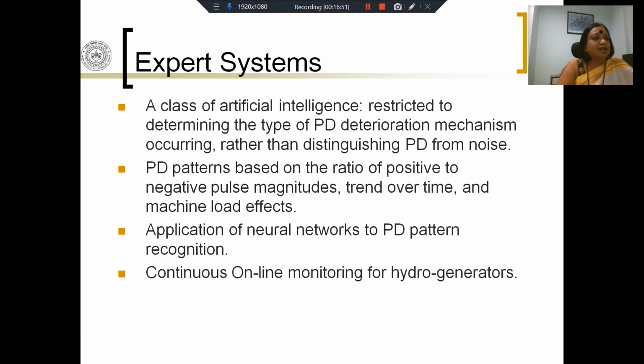And the main thing that is to be said about partial discharge detection is that we have the measurement techniques. What we do not have are foolproof interpretation strategies. And therefore, what we still need to do is we need familiarity with the patterns for every kind of fault so that we can correlate them when that happens. So PD detection techniques generally take the help of expert systems.